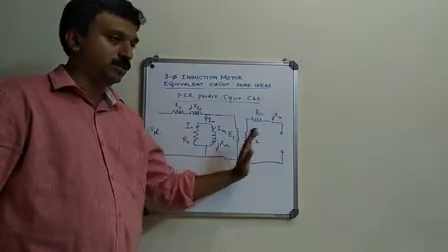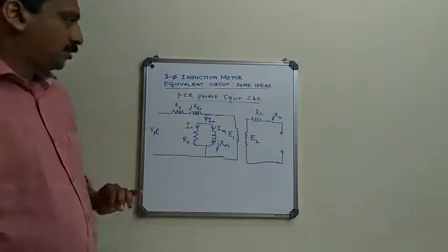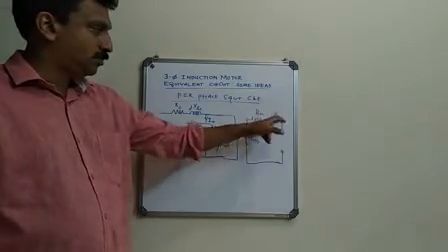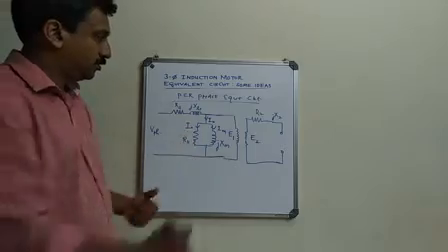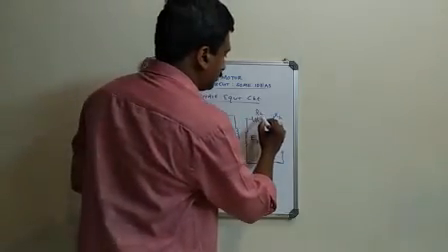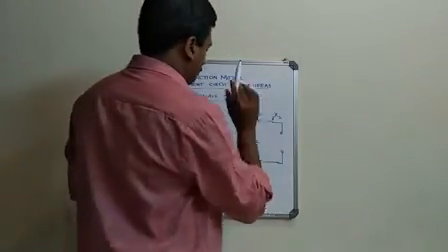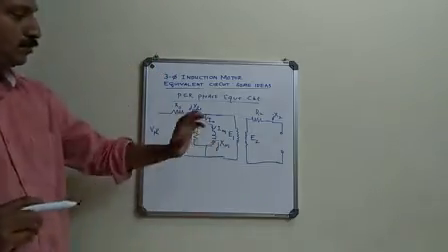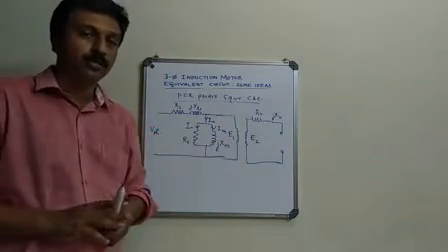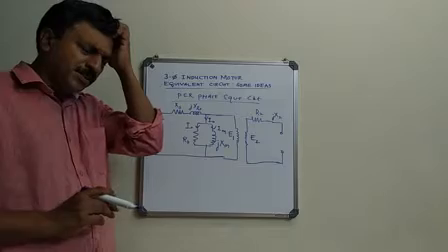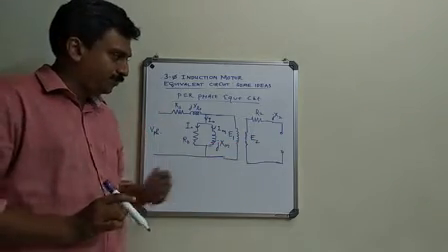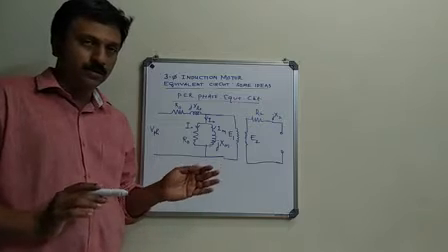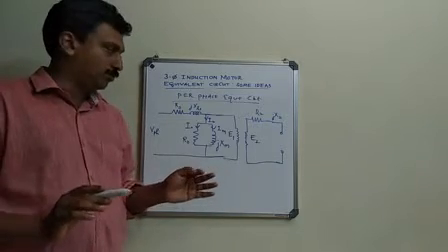Here it is stator and rotor. Now this notation I used in a similar way. There will be some rearrangement and another notation. And see that it is open circuit, it won't rotate. So in this case it is equivalent to a transformer.